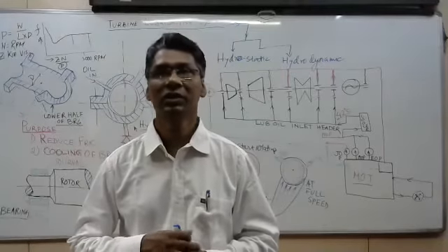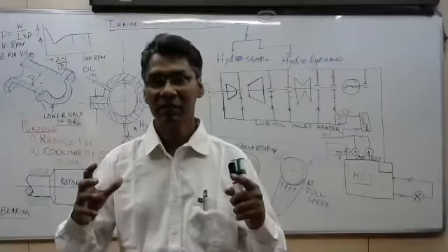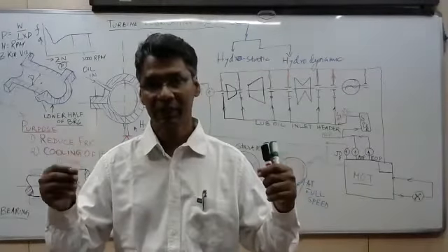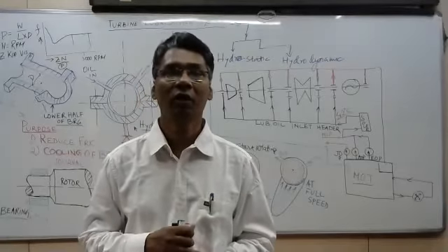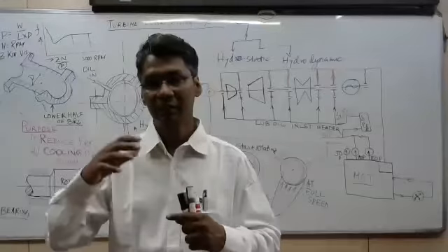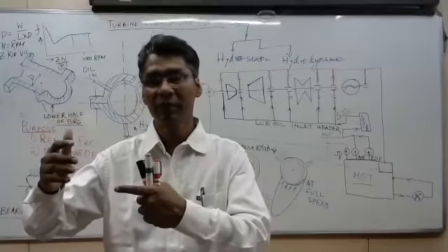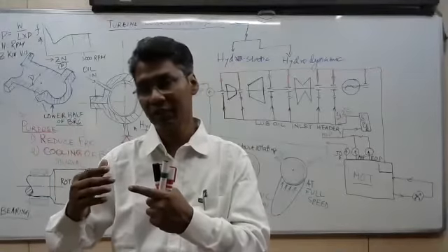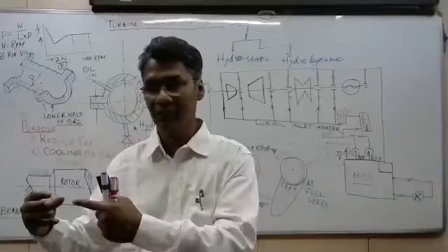And the second objective is cooling. Cooling means the turbine is rotating at 3000 rpm. That too, the turbine shaft is handling a fluid of, suppose, 540, 600 degrees centigrade. Itself, it is in contact with 600 degrees centigrade steam while the rotor is rotating. So the metal temperature is also achieving up to 500, 540 like this. So the bearing also comes up to some higher temperature.